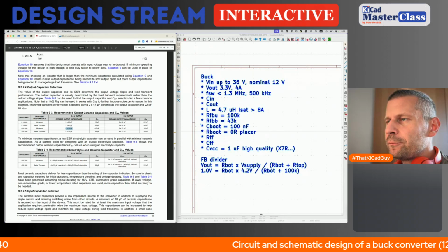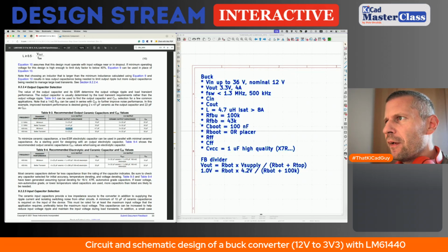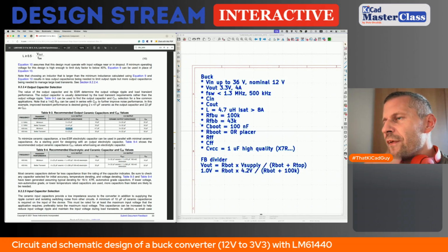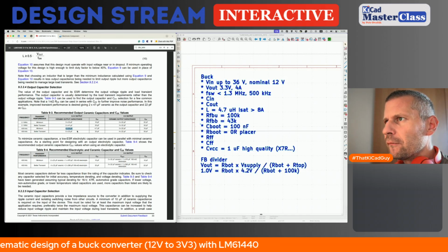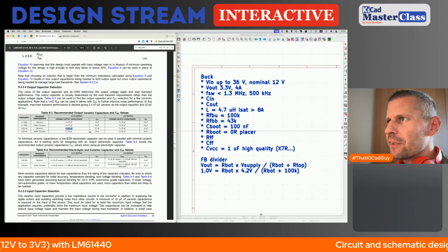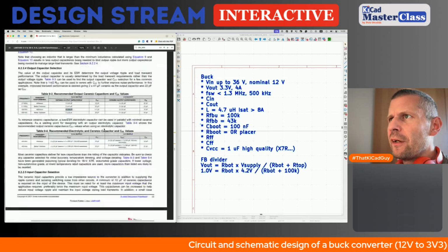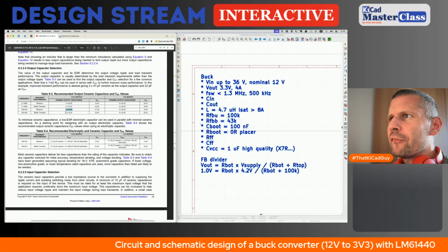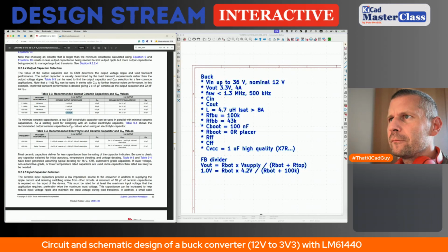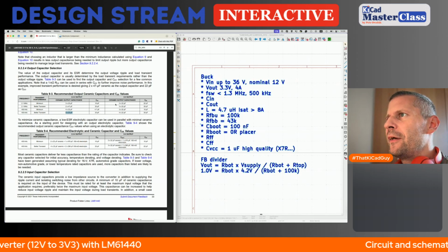So the total capacitance is basically the same, but they work with probably different parasitic parameters like ESR or something. Unfortunately, there is no calculation, but I think we will go with the better transient. We will use 5 pieces of 22 microfarads.